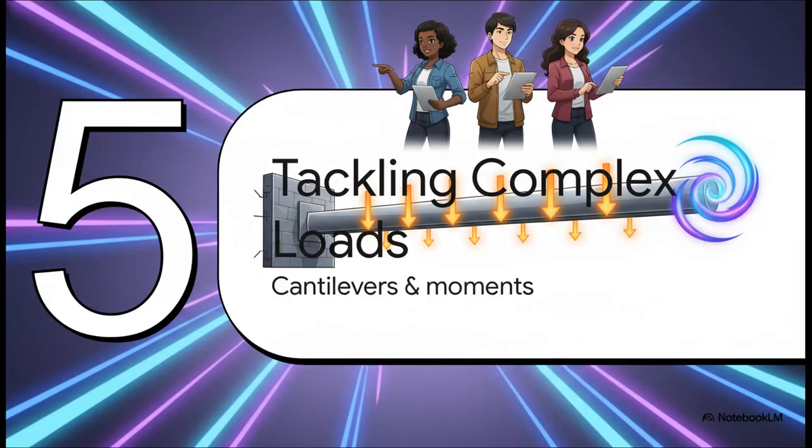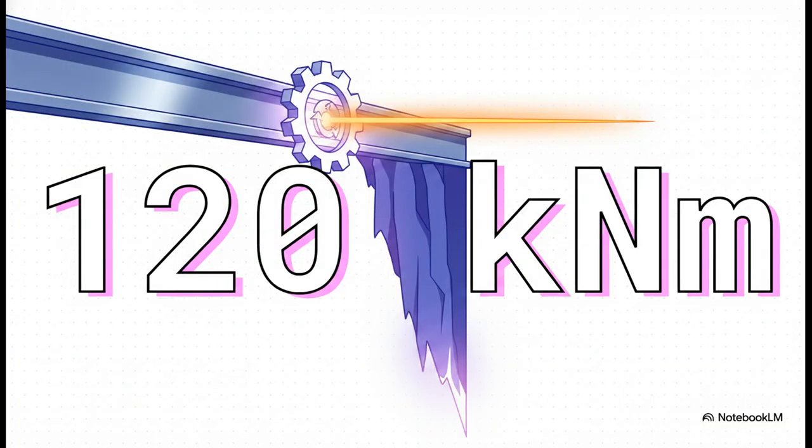Which brings us to Section 5, Tackling Complex Beam Loading. Simple point loads are easy enough, but real life is messy. Let's apply those cheat codes to a real boss battle scenario, a cantilever beam that features both a distributed force and a concentrated moment. Imagine you're mapping your beam left to right, and suddenly, wham, you hit a concentrated applied moment of 120 kilonewton meters. What happens? Well, it causes a sudden, dramatic drop in the bending moment diagram. It's a literal cliff edge on your graph.